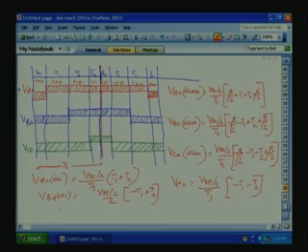So this way, substituting these values into the equation, we can find out the average voltage variation, and from the average voltage variation we can find out whether the average space vector is tracing a circle, or if the average voltage variation for the phases are sinusoidal, then our PWM is achieved, space vector PWM is achieved.